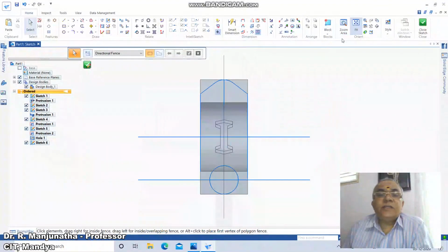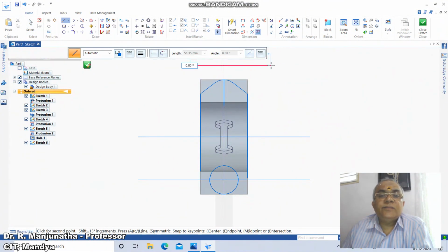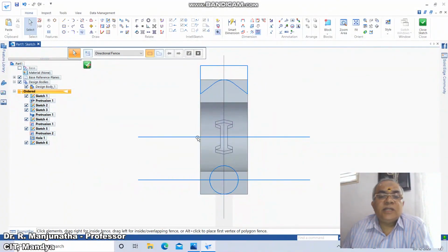then you fit it and take line and take some line extra here and go to trim corner between this and this, between this and this, between these two. Now similarly, join by joining between the trim corners of these points. So once you do that, now we are going to delete this and also delete all these things. Now we will try to mirror this.